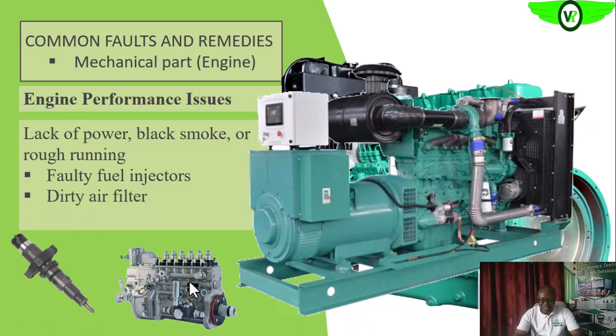Then a dirty air filter prevents the required amount of air from getting into the combustion chamber. So that will now affect the air fuel ratio. Okay, the air fuel mixture will be affected, and that will affect the energy that will be consumed, because it can result in incomplete combustion. So the energy that will be extracted from a definite amount of fuel will be reduced, and that will affect the performance of your engine.